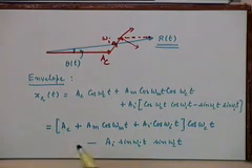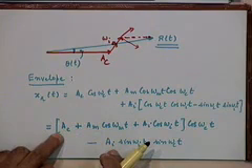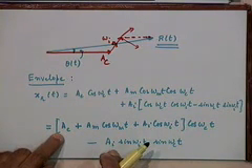Now we have had some discussion of the behavior of the envelope detector under these kinds of conditions. Do you remember we discussed this in some other context? In the context of demodulation of SSB and VSB signals by the carrier reinsertion method, right? So it's the same kind of situation here. If this is much greater than this, the envelope will be dominated by which term?